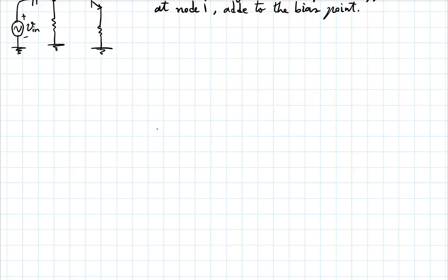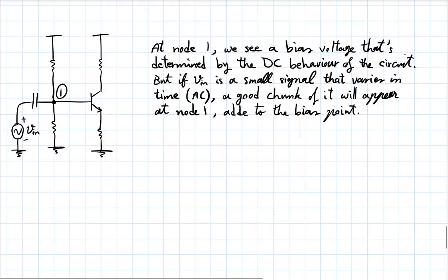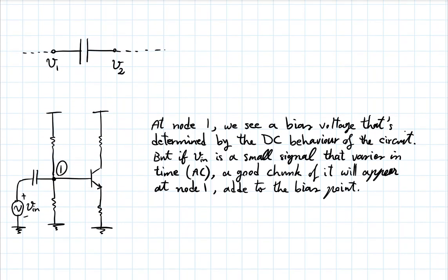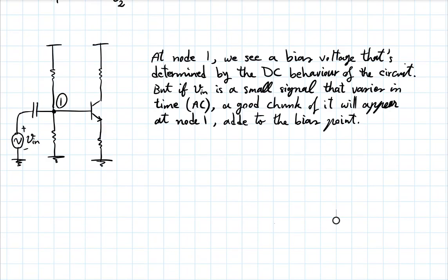But anyway, like I said, AC analysis is not really part of our discussion. But we want to just take this from me: this is where AC analysis of transistor circuits starts. You use this kind of coupling capacitance to feed your AC signals in. And in fact, the answer is that for this kind of coupling, you want a large capacitance. But anyway, we'll talk briefly about it a little more next time.